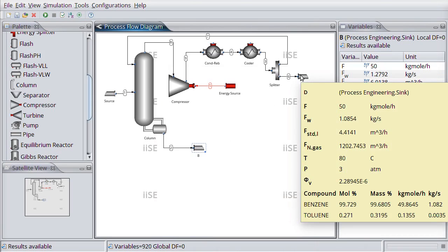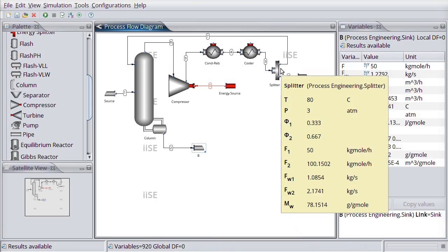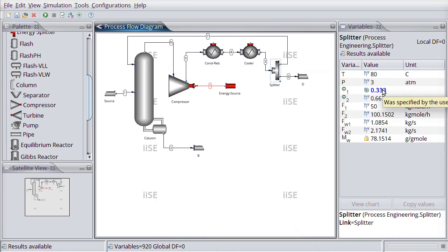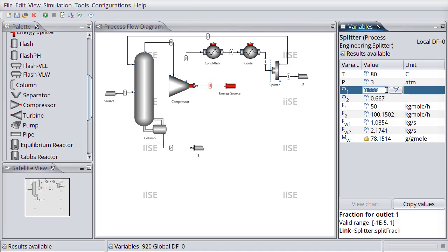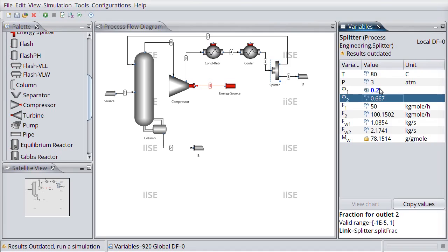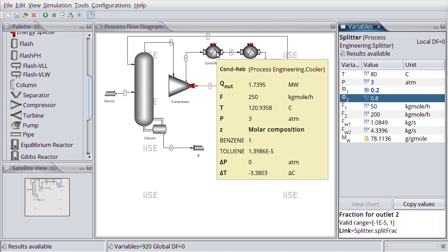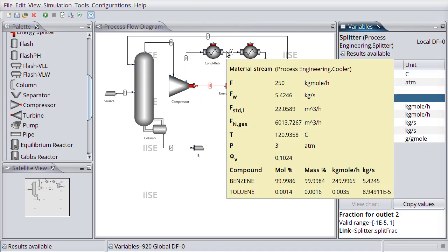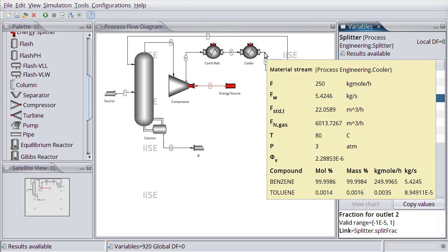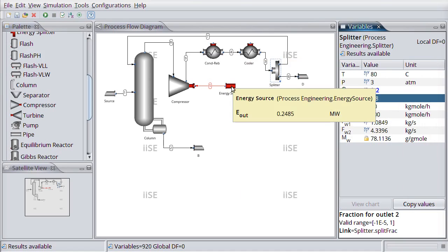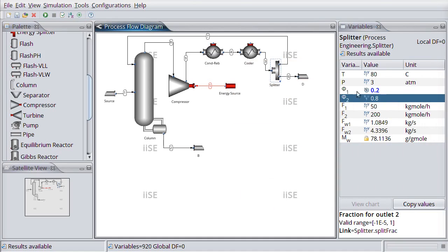Now any modification we add to the simulation will take into account this energy reuse. Let's say we change our reflux ratio. I will increase the reflux ratio by reducing the split fraction for the distillate. Now we need more heat on the reboiler and we'll remove more heat on the condenser. Temperature is 112 degrees Celsius for this case. Plenty of temperature to reuse in our reboiler.